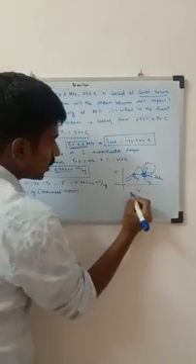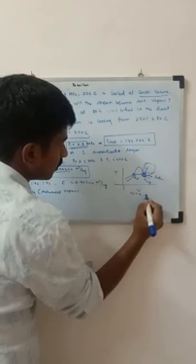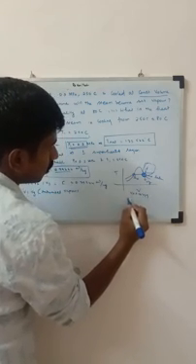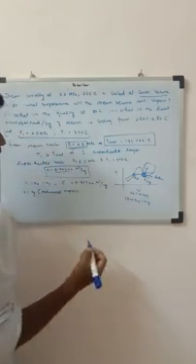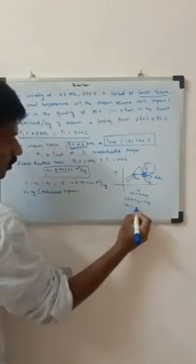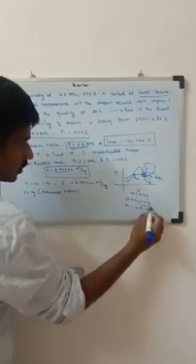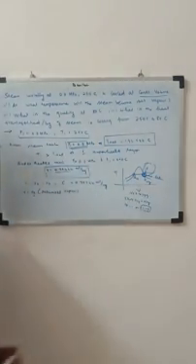If it is in this region, it is Vf plus x into Vfg, or 1 minus x into Vf plus x into Vg. So that means when x is equal to 1, V is equal to Vg. That is my saturated vapor point. That is this point. So my V is Vg.